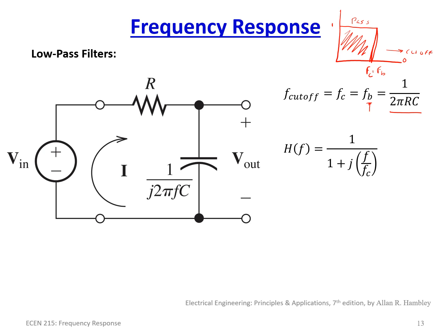By doing this, you're able to simply know what FC is in terms of hertz, and you don't have to constantly compute 1 over 2 pi RC. You just call this whatever the frequency is. You know, the cutoff frequency is at 1,000 hertz. Once you know that, then you can work your transfer function. The useful thing about this is that usually you're trying to set the frequency cutoff to a specific frequency, so you're going to want to create your filter to set to some FC.